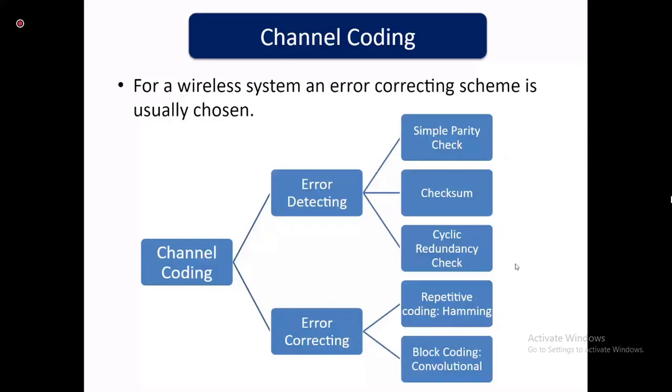It stands for Long Range Wide Area Network, and it can only send 51 bytes at a time. So that's not really a large data volume, and the probability that there will be erroneous bits in that is pretty low, which is why we go for error detection systems.